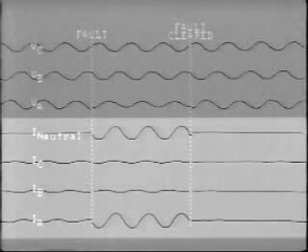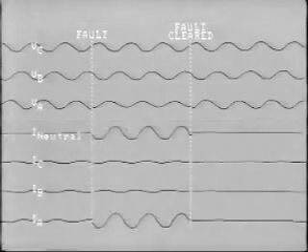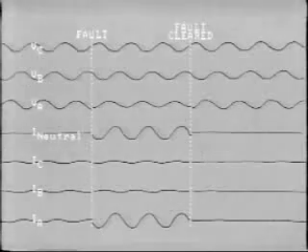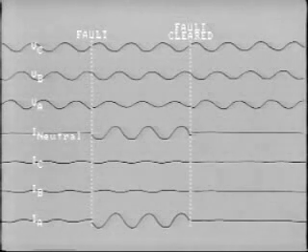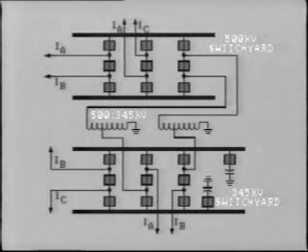The current traces can then be compared with voltage traces to confirm which phase or phases were faulted. A sharp rise in current and drop in voltage on A phase, for example, is a pretty sure sign of an A phase fault. Often there are not enough channels to monitor each phase current of every important line. So, quite often, only one phase of each line is monitored, with the phases alternating from one line to another.